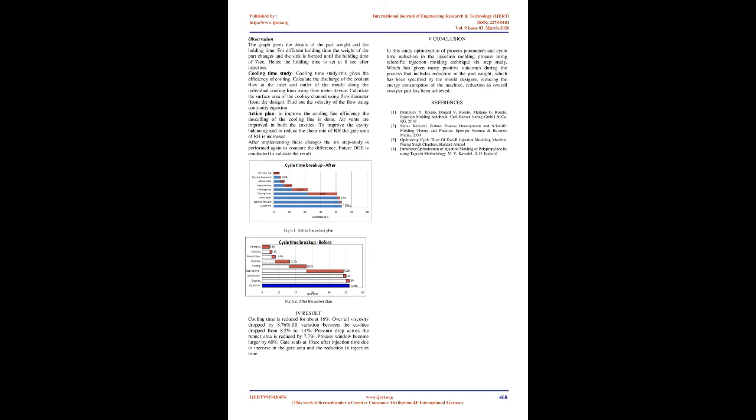Observation. The graph gives the details of the part weight and the holding time. For different holding times, the weight of the part changes and the sink is formed until the holding time of 7 sec. Hence the holding time is set at 8 sec after injection.